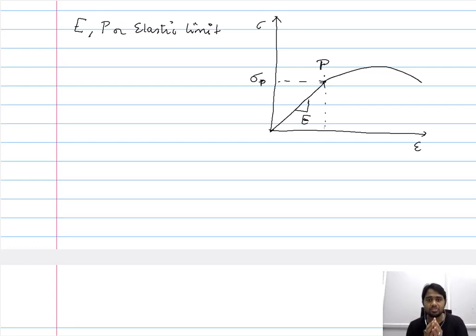Now that we have understood what plastic deformation is, in the previous lecture we saw that plastic deformation is governed by the increase in the number of dislocations and also the average distance covered by the dislocations. So in addition to being a theoretical concept, the elastic limit is also the maximum stress at which there is not much discernible mobility of the dislocations.